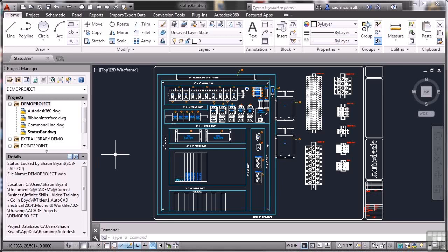That is part of your status bar, and it tells you the X and Y coordinates of the location of the cursor. Now, if we were working in 3D, creating a 3D structure or a 3D object, those coordinates are much, much more important. In AutoCAD Electrical, we're going to be creating 2D schematics of components, panels, and so on. So we won't really need to worry too much about our coordinate readouts. However, sometimes they may come into play to locate a certain circuit board, a certain master switchboard, or a junction box, for example. It depends on the environment in which you're working.